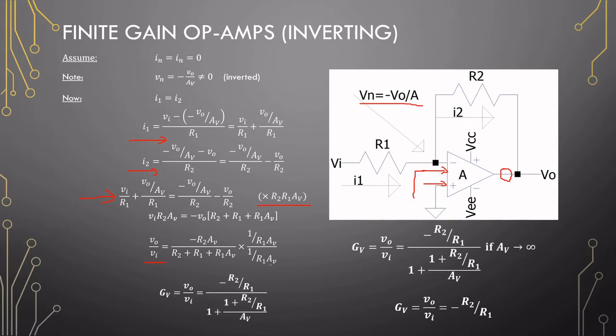And lastly, the addition of this step where we basically multiply by 1 is to get our amplifier in the form that we have minus R2 over R1 on top, which is our regular gain when just using feedback resistors. Okay, so the top is the gain that you're aiming for, and then the bottom is the adjustment for the amplifier's finite gain.